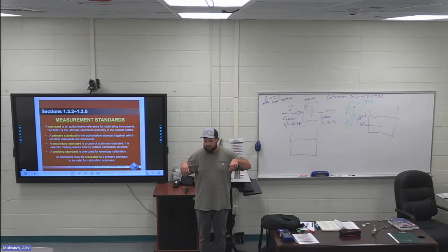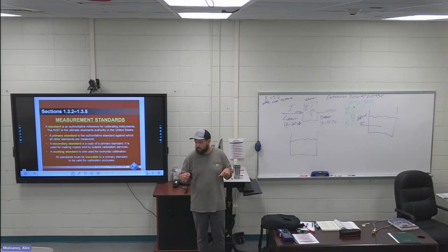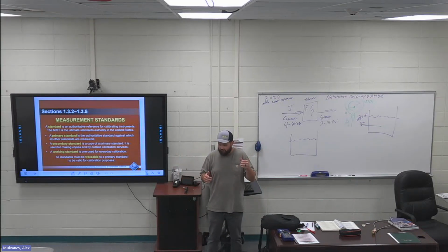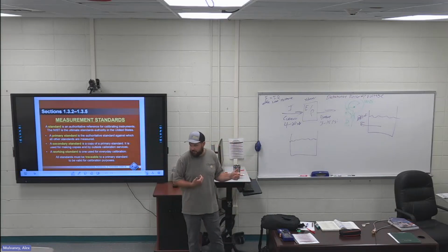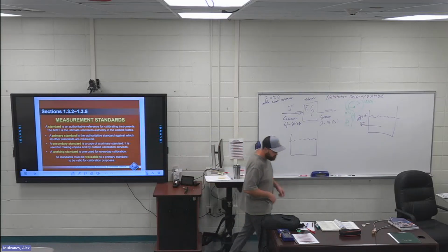What am I detecting? Change in pressure to determine a flow, pressure to flow, inferred measurement. I know that if I have 100 pounds of pressure on this side and 50 pounds of pressure on this side, it's this amount of flow through this size pipe in these calculations. Inferred measurement.